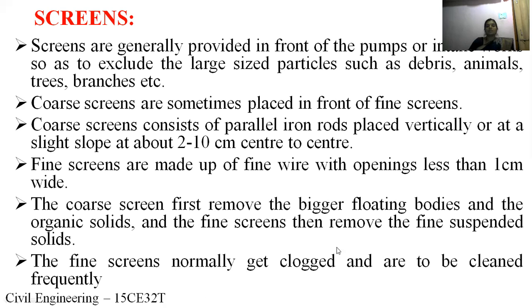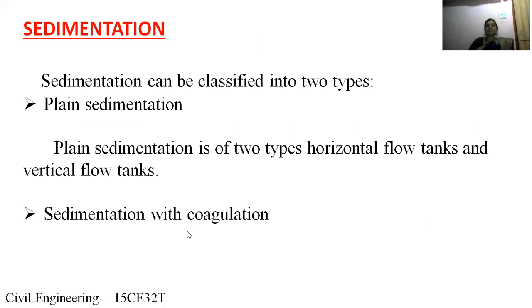When the clogging happens, we need to clean it. Next topic: sedimentation. Sedimentation can be classified into two types. One is plain sedimentation, another one is sedimentation with coagulation. Plain sedimentation is again classified into two types: horizontal flow tanks and vertical flow tanks.